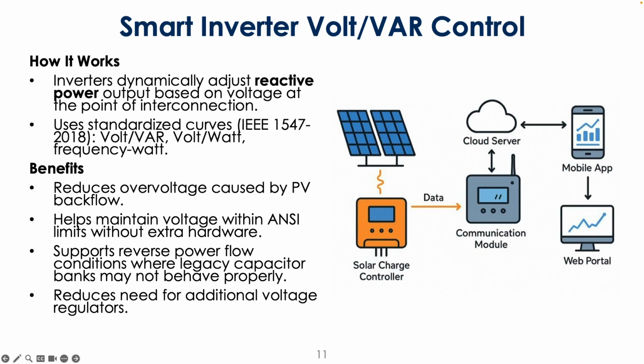These inverters are designed to help mitigate some of that. They adjust reactive power output based on the voltage at the point at which you're interconnecting your DER. So a lot of that backflow issue that can push voltages higher than allowable, this can help reduce. It can also help maintain voltages within certain limits.